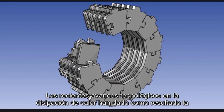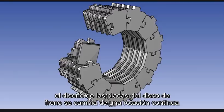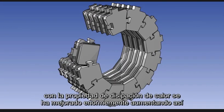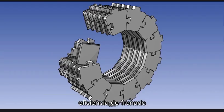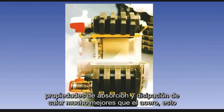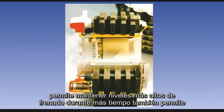Recent technological advancements in heat dissipation have resulted in the design of the brake disc plates being changed from a continuous rotating single plate to a plate constructed of many interconnected individual segments, with the heat dissipation properties being greatly improved, thus increasing brake efficiency. Carbon is now often used for manufacturing brake units because it has much better heat absorbing and dissipating properties than steel. This allows higher levels of braking to be maintained for longer.